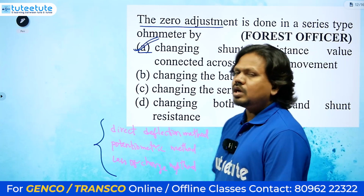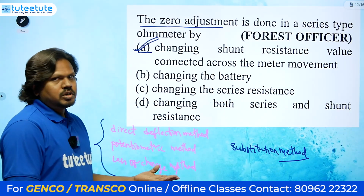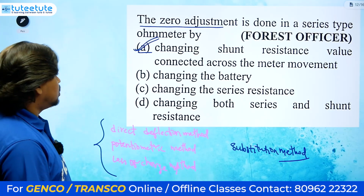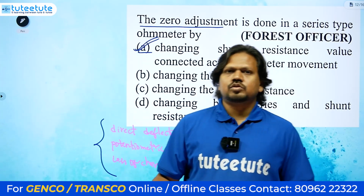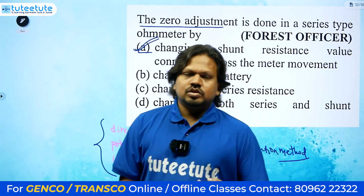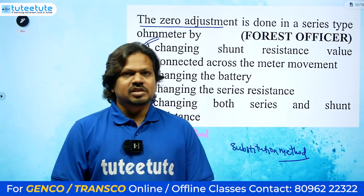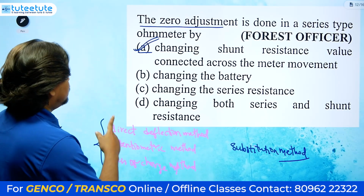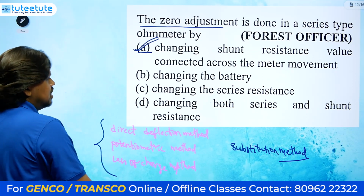If you are working with underground cables, you sometimes need to use the loss of charge method, and there are Megger applications in underground cables too. Otherwise, internally in the power plant, if you are working there, you need to carry some devices for measurement purposes. That's why these methods are important for us. Anyway, the answer for this question is changing the shunt resistance value connected across the meter movement.